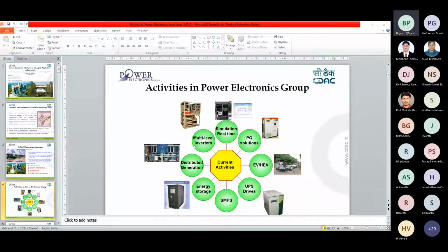You can classify microgrids in different ways, like by operation. Based on its operation, you can classify it as an off-grid microgrid, or, if you are complementing a big grid, and what we define as a weak grid is a grid with frequent interruptions, if your microgrid can work together with such a grid, you can term it a grid-supporting microgrid.